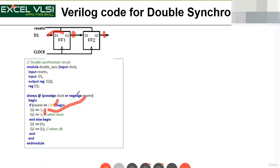Usually reset will come first and you reset the system. After that you bring it out of reset, and then the circuit has to work with respect to the clock. Initially during reset, you are making both flip-flop outputs 0. Then on the next clock, D1 you are giving to Q1, and Q1 you are giving to Q2.